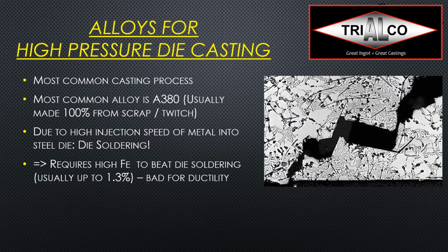But at the same time, if my iron gets too high, and even when you have A380, you should check your chemistry from time to time. I have seen A380 castings and they were not A380 anymore. They were actually much higher. They even had 3 or more % iron. And then you can get things like this, where the iron needles are actually platelets in a 3D space. They are so connected that they would just lead one crack all the way through the casting.